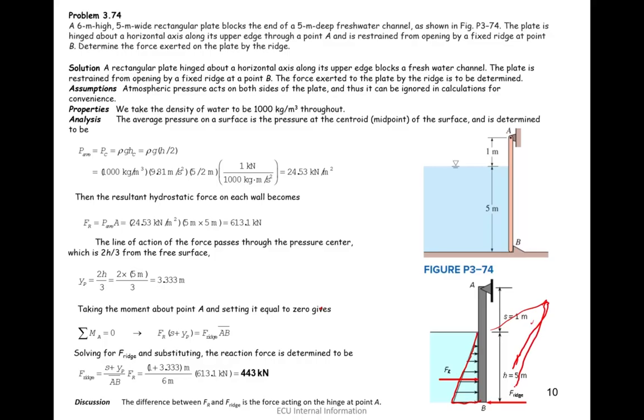Then you can see that means the pressure is like a cube in here, and if you work out the centroid of that triangle, then it gives you where the force is acting, because this triangle shows the distribution of pressure.